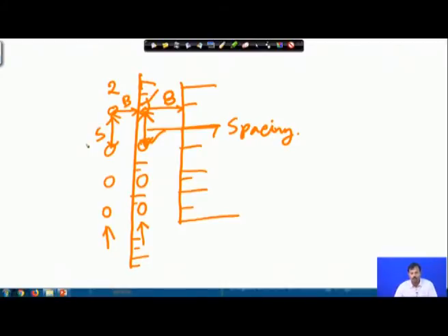So, always the burden is the distance from the free face to the hole, or from the new face created for the second row of holes to the second hole position. The spacings are the distance between 2 adjacent holes, which does not show any resistance. But where is the importance of the spacing?